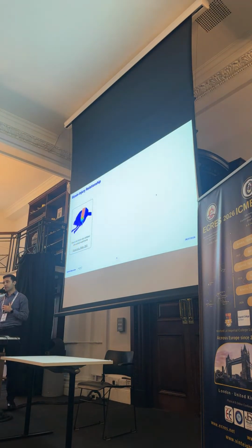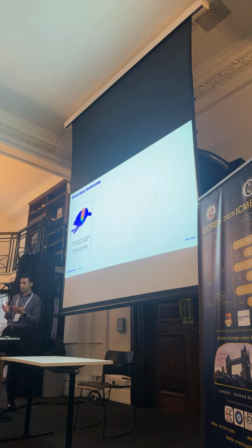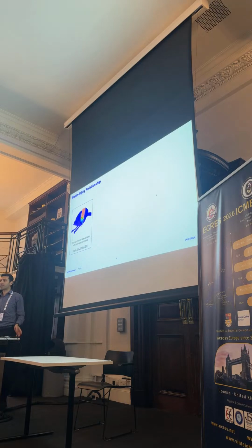So we have been doing several studies in the last 10 years on understanding the link between strain, and here by strain I mean maximum principal strain and Green-Lagrange strain, because we are dealing with nonlinear mechanics here. So we are predicting Green-Lagrange strain and the maximum principal value of that across the brain over the duration of the collision or the impact.